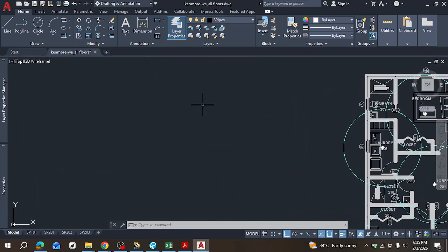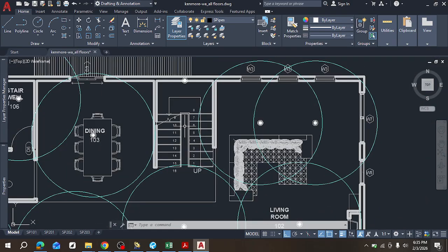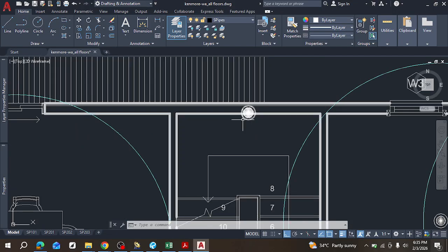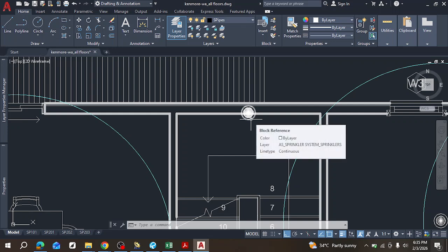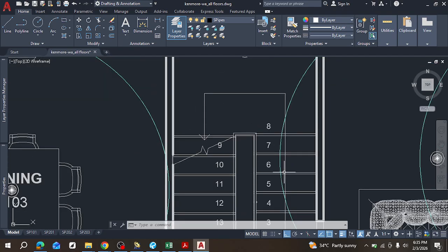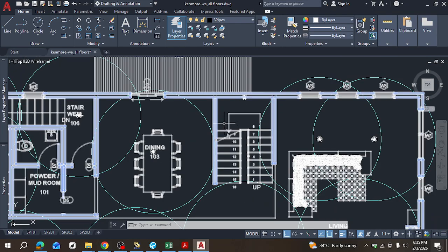So the importance of this now means that there's going to be an area around where there's no ceiling to install sprinklers, and most of the sprinklers we use are ceiling installed, right? That's why there's also the importance of having other types of sprinklers. So in this case, I chose to use a wall mounted sprinkler. So at least you are sure that this wall is going to have entire coverage over this space. At least it's going to protect it to an extent, because there's no particular ceiling that can handle this place entirely.